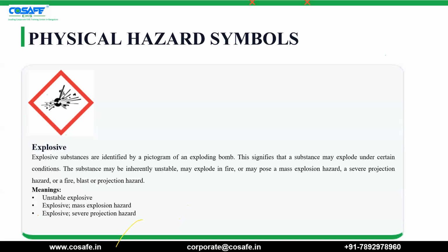See, I'll tell you simply. If you have a storage of 1,000 liters of petrol in your vicinity, and you are storing it in different containers, then the requirement of explosive license doesn't apply to you. But if you are storing that 1,000 liters in a single container, then you have to apply for an explosive license. If you are storing in different containers, then you don't require it.